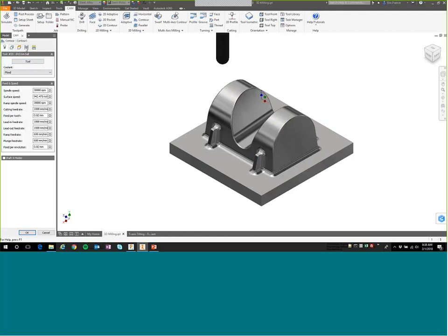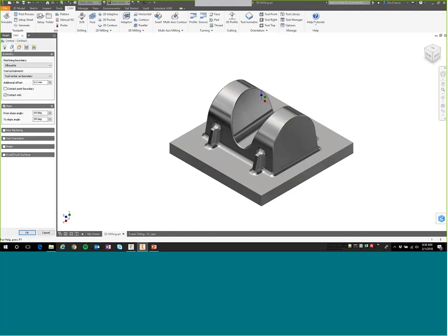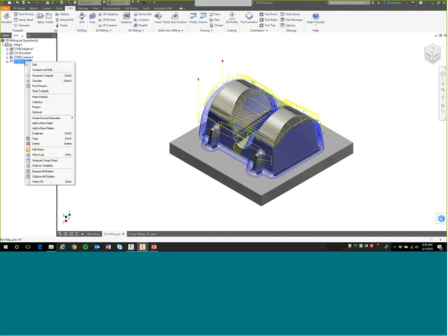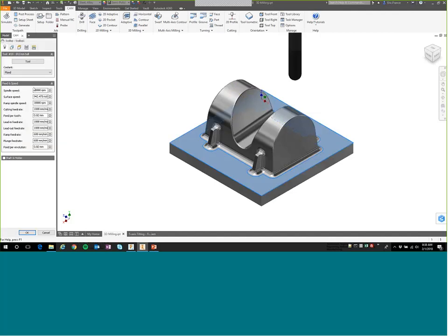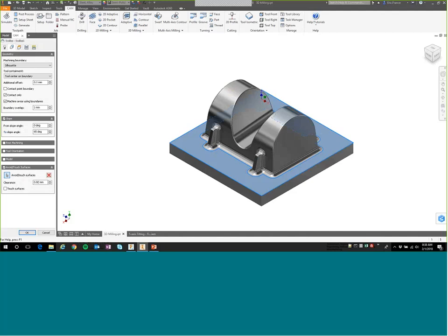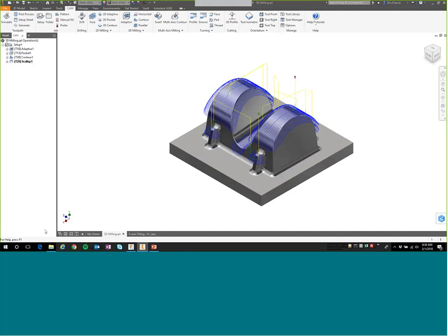It could with the default settings, but we have the ability to identify slope. So we're focusing on 90 to 60-degree slope for the contour. And then for the scallop, we're going from 0 to 65. We want a little bit of an overlap so that it handles that appropriately. But being able to control that, again, contains the tool to those particular areas.